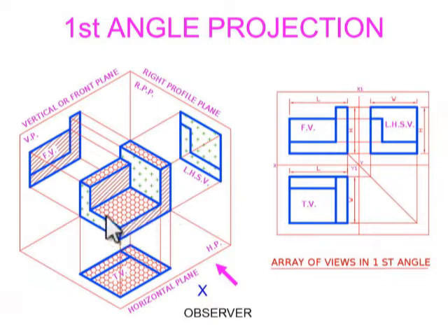Here the object is a three-dimensional object which is having three patterns representing the front view, the top view, and the side view. So here is the final diagram which you are getting as the front view. Now compare this diagram with the pattern diagram which is drawn here. If you are seeing from the front, I have already told you that it is the image which is obtained in the vertical plane. This is the vertical plane.